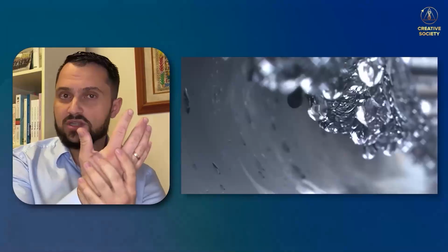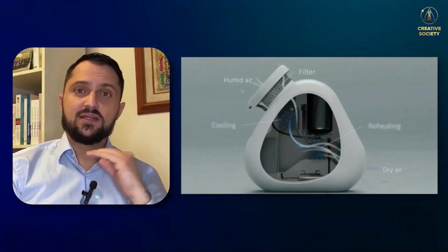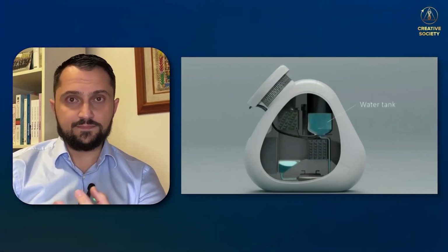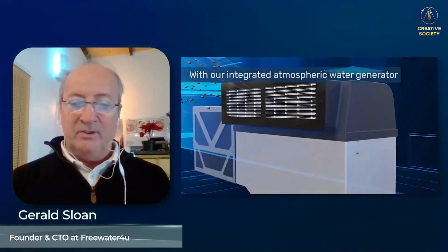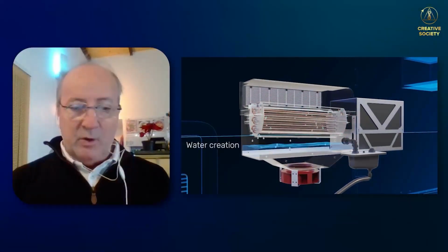At the moment, there's two methods really of obtaining water from the air. One is through the use of a medium, like a mesh or a desiccant that you put through the air, and it basically either absorbs it or forces the condensation through that. And the other one is basically lowering the temperature of the air to the dew point so that the water naturally condenses. The technology there can create water anywhere because heating and cooling creates condensation.